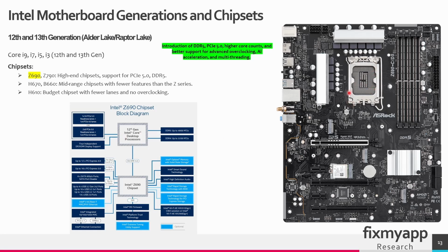We have the CPU, we have the VRMs, the RAM slots, the 24-pin ATX power connector, the CPU power connector, we have the back-end connectors, we have the audio part, the M.2 part, the PCIe slot, the chipset underneath a heatsink. Physically, it's still the same motherboard, so that will make it easier to identify the components, and that makes it easier to troubleshoot.